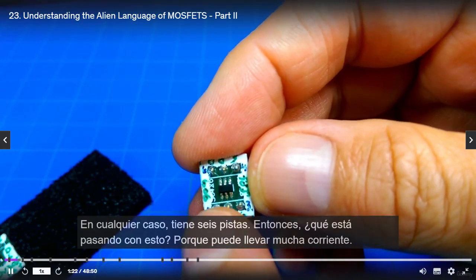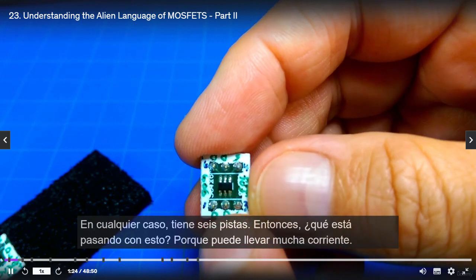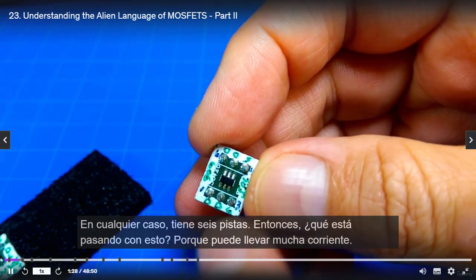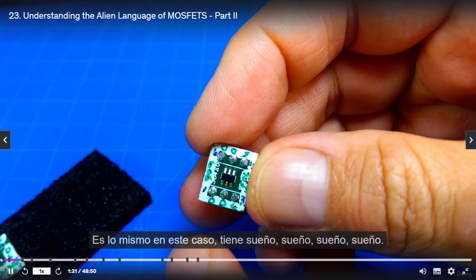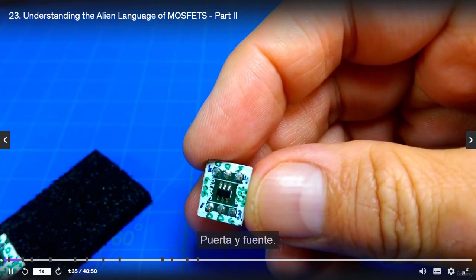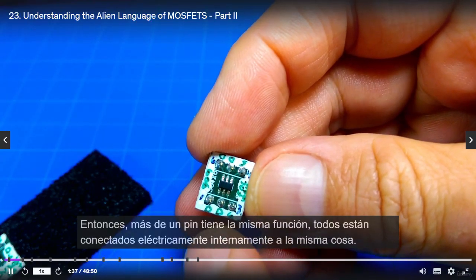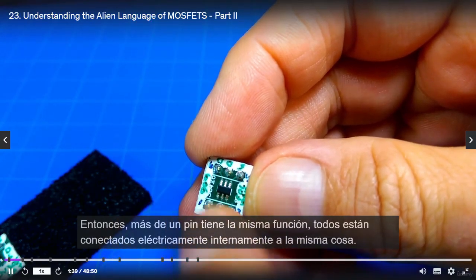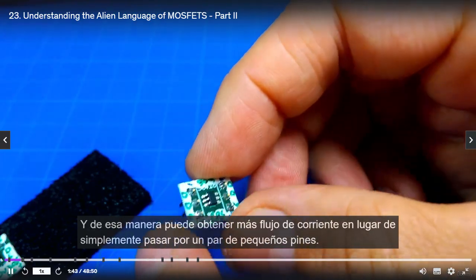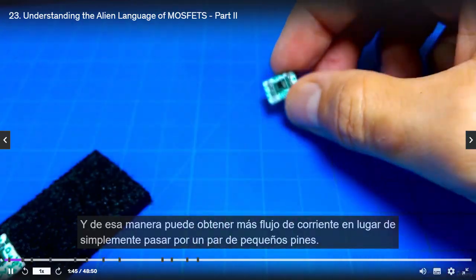In any event, it has 6 leads. What's going on with this? Because it can carry so much current, it has more than one lead that's the same. In this case, it's got drain, drain, drain, drain, gate, and source. So more than one pin has the same function. They're all electrically tied internally to the same thing.